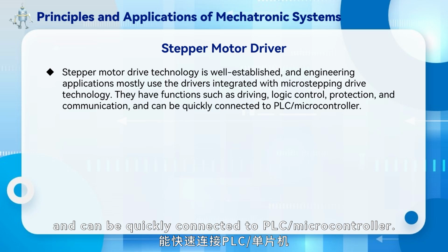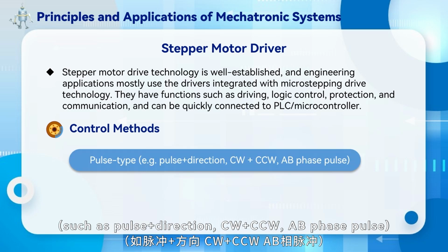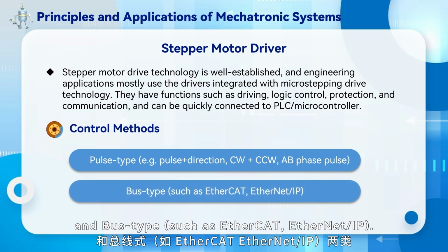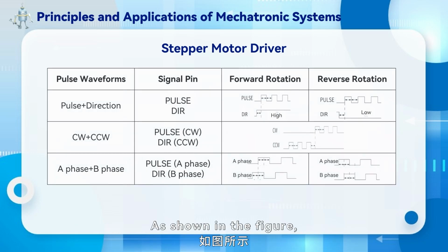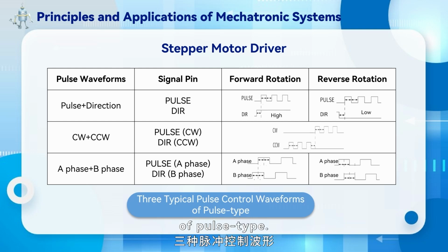It can be quickly connected to PLC or microcontroller. Control methods include pulse type, such as pulse plus direction, CW plus CCW, AB phase pulse, and bus type, such as EtherCAT, Ethernet IP. As shown in the figure, there are three typical pulse control waveforms of pulse type.